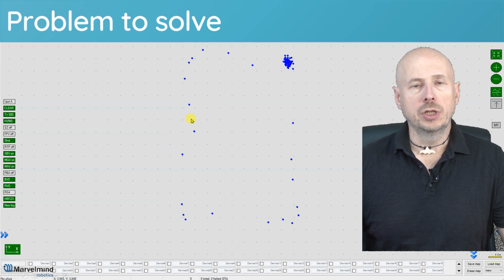But we specifically moved very, very quickly just to show that the distances between the dots may be comparable with how curvy the path is. When I have a smooth track, like, I don't know, an ellipse, it wouldn't be a problem. But when I have sharp curves and sharp turns, then the update rate may not be enough. And the only solution is to increase the update rate of the location system.